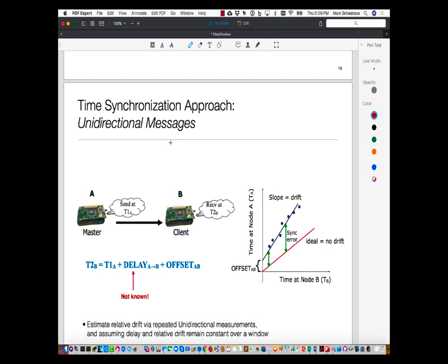I may tell the underlying radio to send this packet out, but if it's a duty cycle type radio, then under the hood it's going to wait until the next transmission episode. That can complicate things. Those are the limiting factors, but oftentimes this is perfectly fine. The other complication is, are you able to do this timestamping at a point sufficiently close to the radio? Oftentimes, we don't have access to the low-level radio.